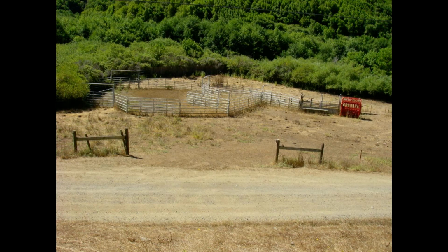The first question in this section is, does runoff from corrals connect directly to streams and rivers? Because of the large quantities of manure around corrals, if there's runoff from those areas, there's likely going to be high concentrations of nutrients and pathogens washed into the waterways. So we recommend redirecting the runoff across the pastures away from the waterways to allow the water to soak into the soil and use plant cover to filter out manure and sediments.